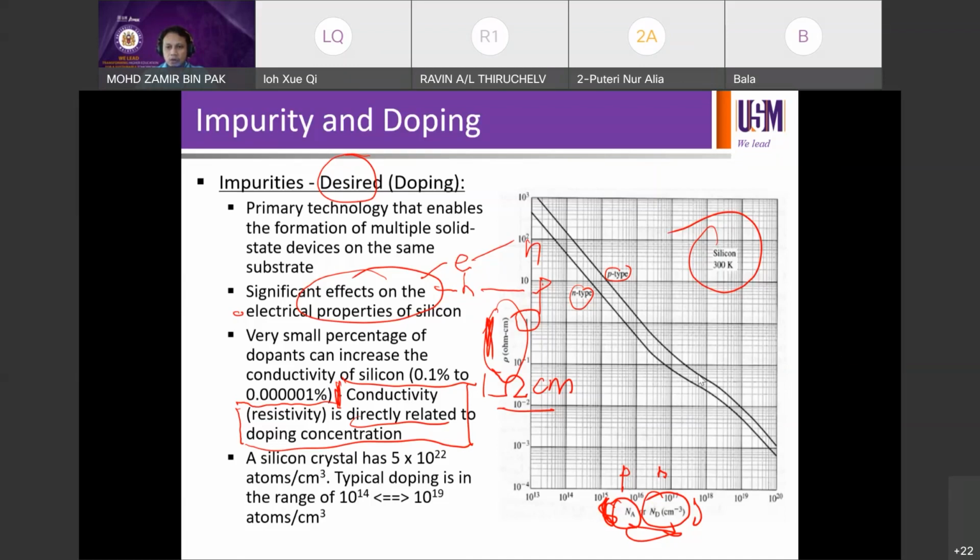Okay, so if you have a wafer with 1 ohm cm resistivity, you can come to this curve. If you're using, for example, a p-type wafer labeled 1 ohm cm, which you take from the cassette in the lab or somewhere else, this is a global reference from the data. So you can already tell the doping level in the wafer from this curve. Okay, so that's the point.